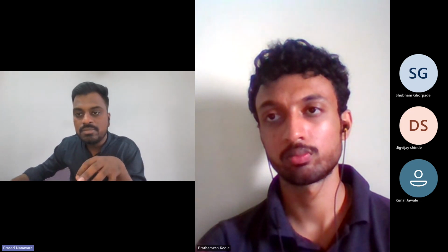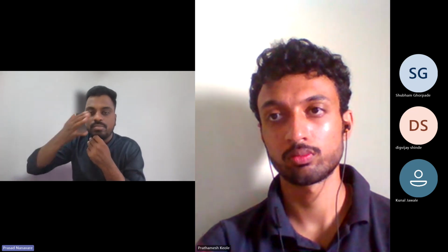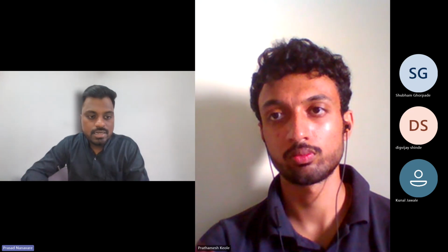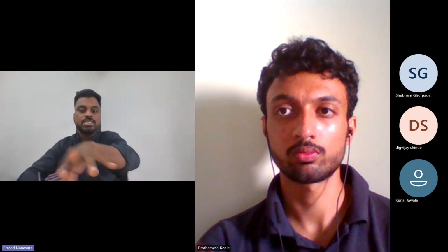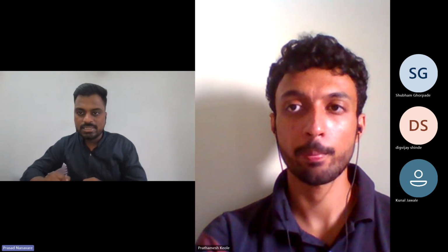Interrupt is an event. Whenever that event happens, a certain action has to take place. After the event has occurred, the normal operation halts and it goes to the interrupt service routine and sees what I have to do now. This event has occurred, now what do I have to do? So this is what interrupt is for. Are you understanding the applications? I gave you two or three examples, right, of what this is used for and what we can do with it. So that is why the interrupt counter is important here.